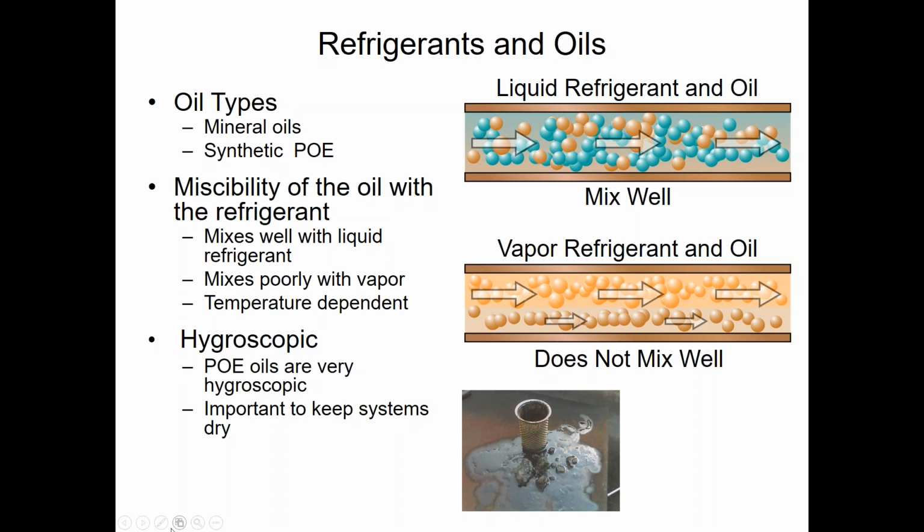And that's part of what our charts are about. Fortunately, we don't have to go in and engineer all this nowadays. We can simply go to our charts and figure out what we need. That's the good part of where we're at today. But I'm pointing out these things so you know how we got to the pipe size, and why we do what we do with risers and everything else, which we'll get into detail in a bit.